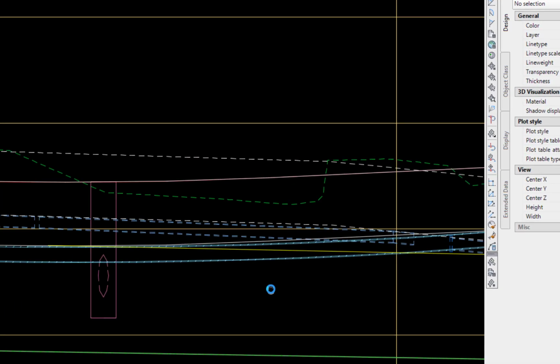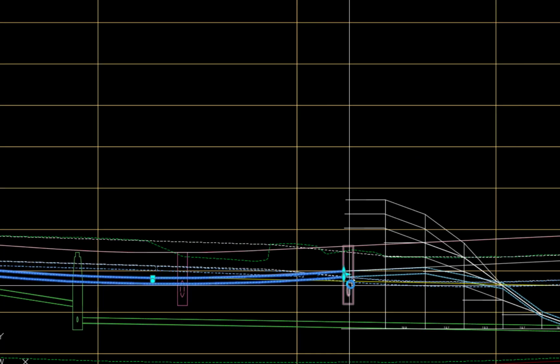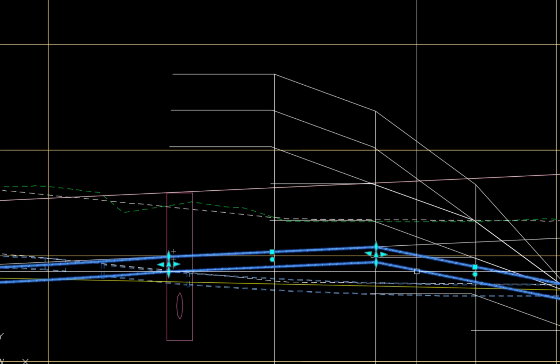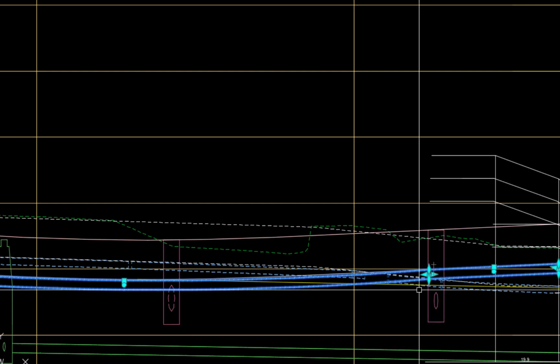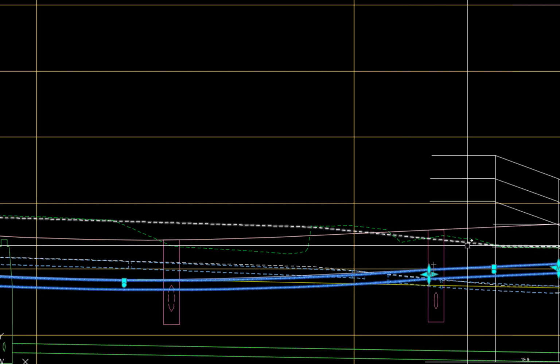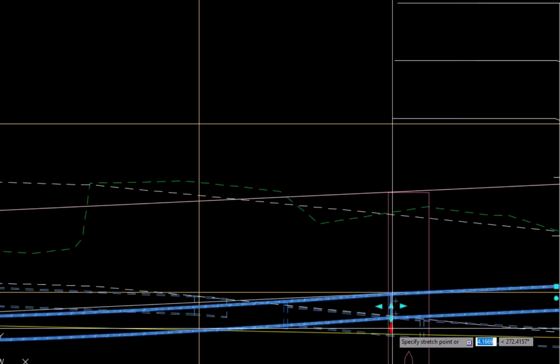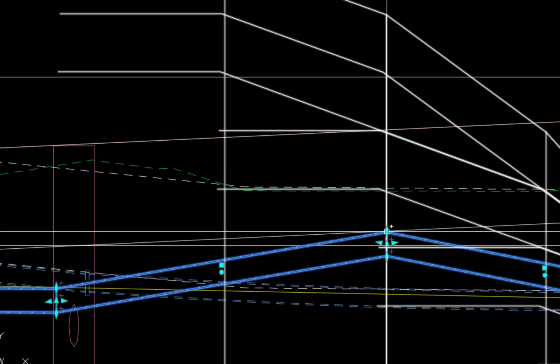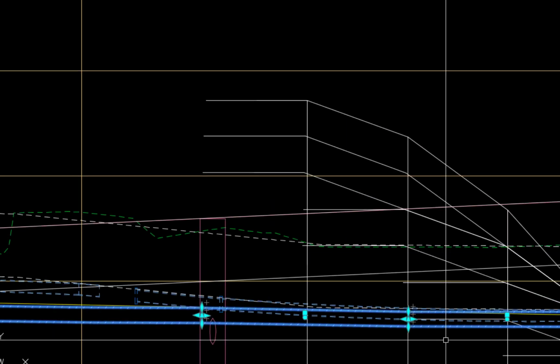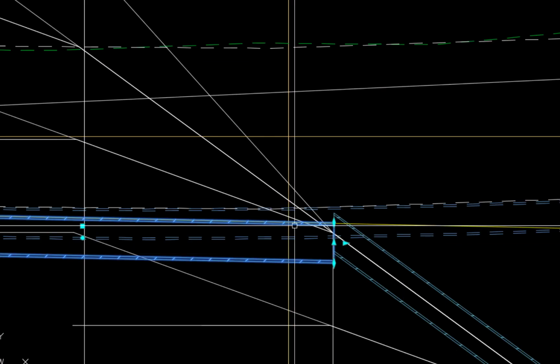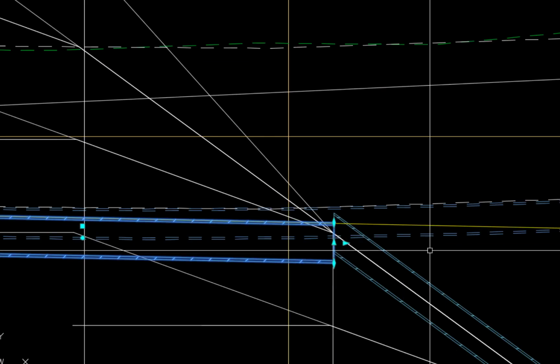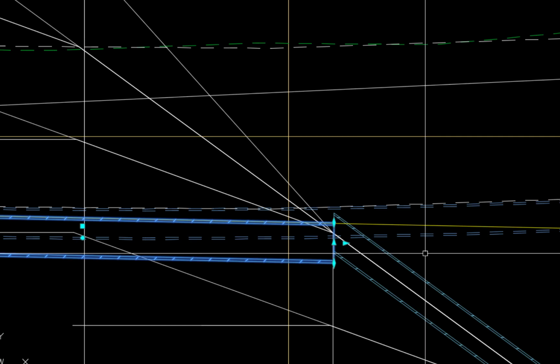Escape. Pick the pipe and use the top glyph at the pipe joints and move down to the yellow line. Visually use the joint deflection template to move the pipe break around 26+05 to where the pipe joints do not exceed the 5-degree deflection.